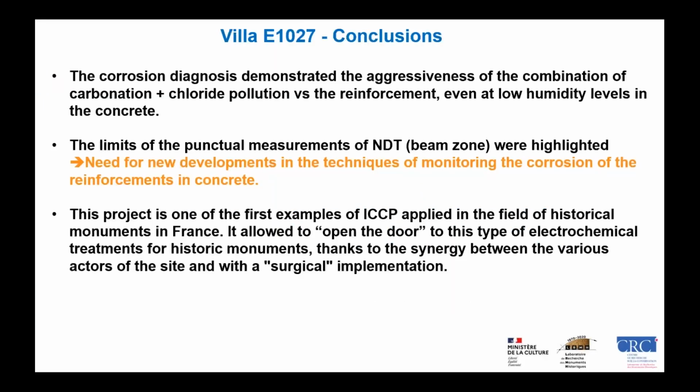So to conclude, we can say that the corrosion diagnosis there demonstrated the aggressiveness of the combination of the carbonation and chloride pollution for the reinforcement, even at low humidity. And we can say that we know already the limits of the punctual measurement of non-destructive testing. There is a clear need for more developments in the techniques of monitoring for the corrosion of the reinforcement of